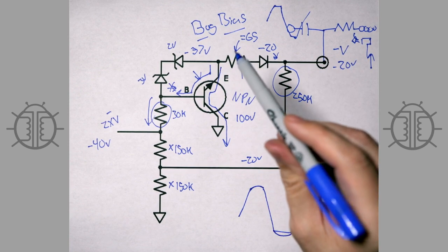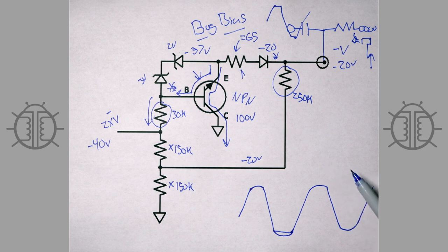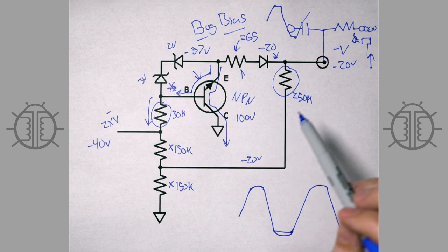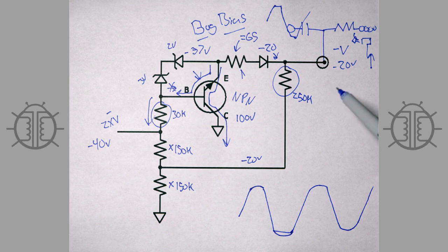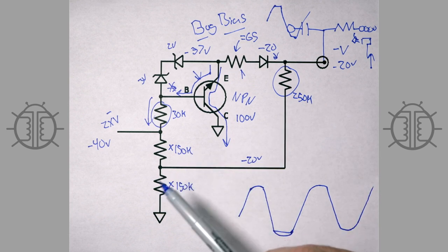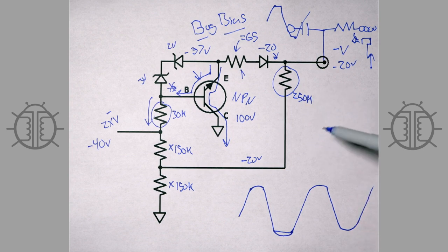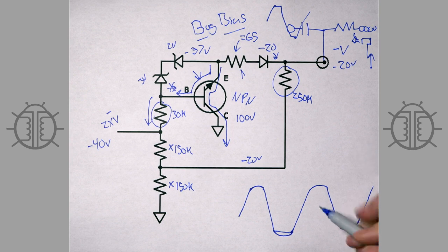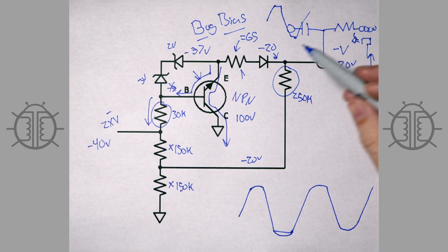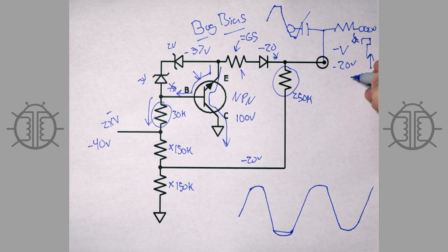I have a PCB that I'm using, but I want you guys to have a look at this, tell me what you think. And so we've tested this, we've put it in amps. Sean has done a SPICE simulation of this circuit. Like I said, I've built it on the breadboard, and this completely removes crossover distortion caused by blocking. It doesn't matter what bias voltage you choose, as long as you adjust it on this side, not on this side obviously, adjust it over here for the desired output right here.